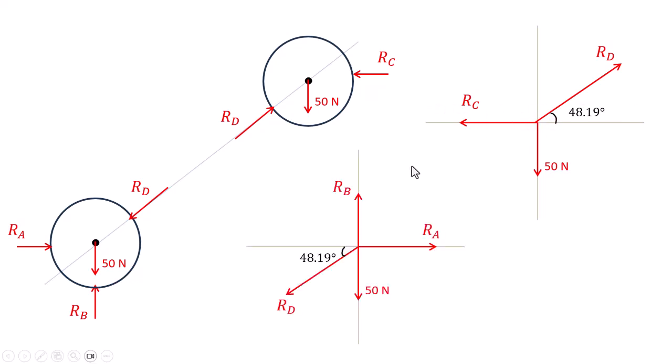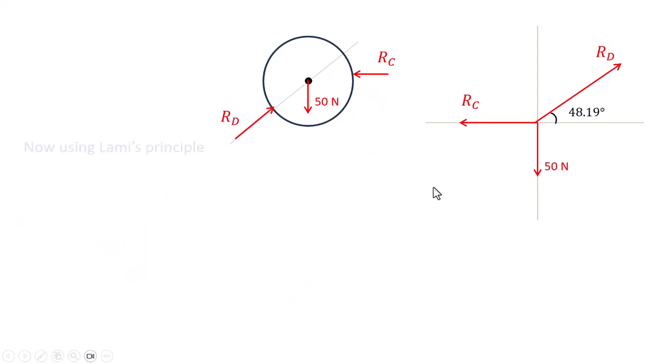Now draw the simplified force vector diagram of the same forces by moving all forces to a single origin point. It makes the problem easier to solve. Now select the cylinder with fewer forces acting on it, as it will be easier to analyze. Here, cylinder 2 is subjected to 3 forces, and cylinder 1 is subjected to 4. Therefore, we choose cylinder 2 for further calculation.